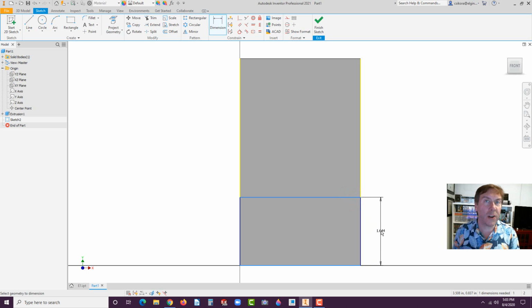Now those of you who are new to making drawings, here's some advice. This isn't a detailing class, but I do want you to know a little bit about the rules. You want to try and make the dimension as easily readable as possible. So think of it as a field goal. And if you want to make sure that field goal makes it, you're going to try for center, especially if there's no blockage.